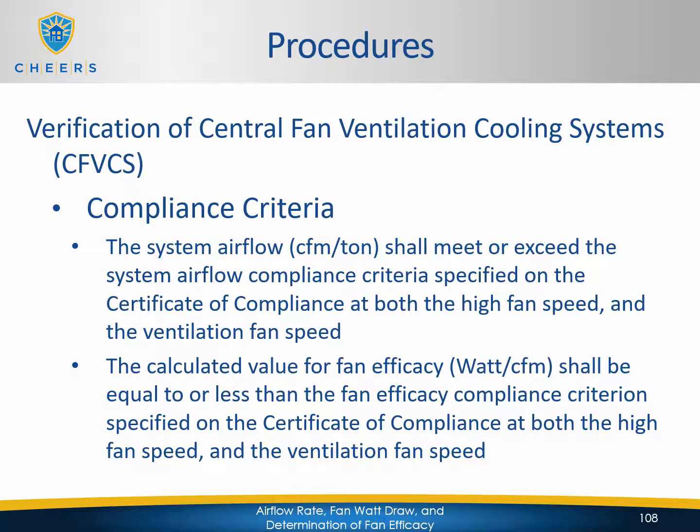In addition to that, the calculated value for fan efficacy, which is the watts per CFM, shall be equal to or less than the fan efficacy compliance criteria specified on the certificate of compliance at both the high fan speed and the ventilation fan speed.